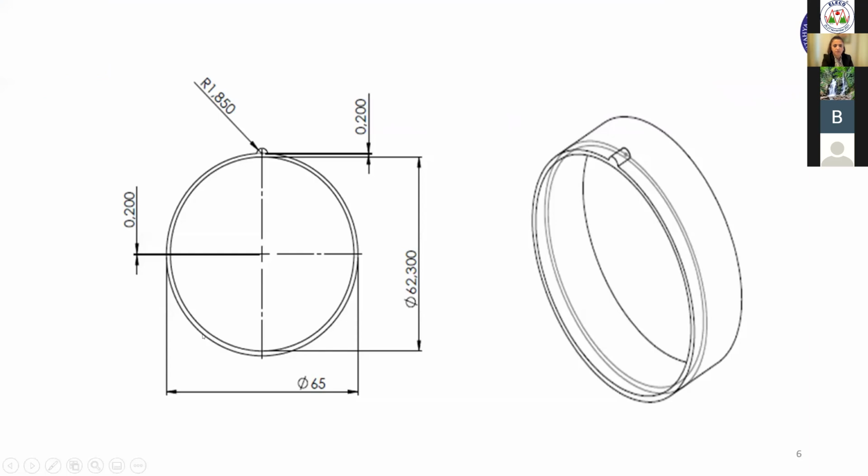The eccentricity fault was implemented in the laboratory by expanding the bearing housing in the end shields of the induction motor. The rotor rotation center was shifted by 0.2 millimeters. Two bushings were designed and produced from PLA material by using a 3D printer and placed in the expanded bearing houses at each end shield of the motor.